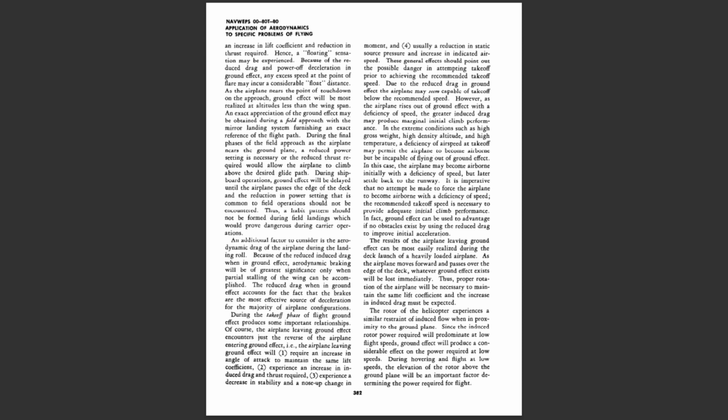The rotor of the helicopter experiences a similar restraint of induced flow when in proximity to the ground plane. Since the induced rotor power required will predominate at low flight speeds, ground effect will produce a considerable effect on the power required at low speeds. During hovering and flight at low speeds, the elevation of the rotor above the ground plane will be an important factor determining the power required for flight.